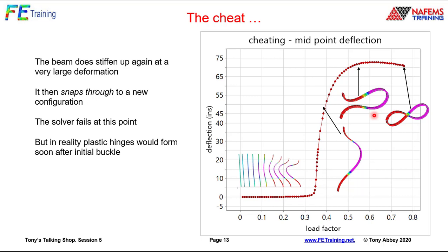And it's an interesting exercise in showing potentially what the nonlinear analysis can show us. It can show us the post-buckling type of behavior, what happens after we actually get that buckling point. Linear buckling analysis can't give us that. Now again, it's a little bit of a fantasy land because I didn't put plasticity in there, but we'll look at that a little bit later on.